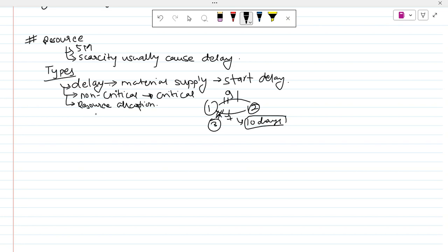So what happens in resource allocation is the peak resource usage. We list the resources. So the peak resource usage, suppose on day 5, is 7, for example 7 man hours. We have only 6 people. This activity and this activity, this is a network, this is a long chain. This is just an activity that I picked.